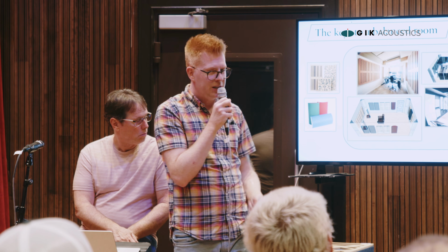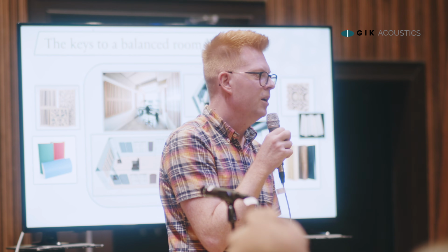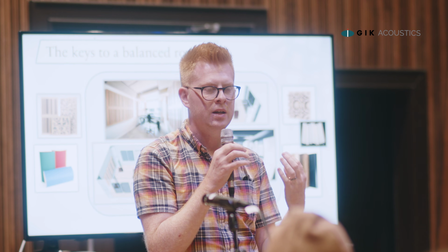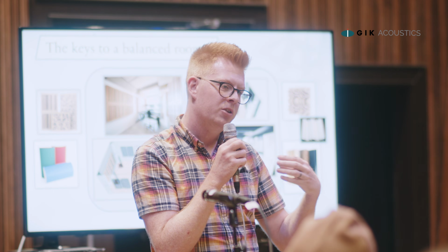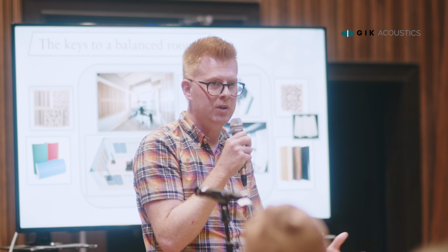Some of them still do absorb, but less so. They're more diffusers in the traditional sense, that the sound is going to be reflected, but not in a specular manner. It's going to scramble the reflections in a way that the energy is kept in the room, but it's not like a very strong reflection coming back that's going to be distracting.